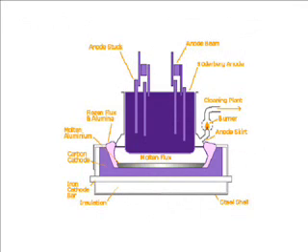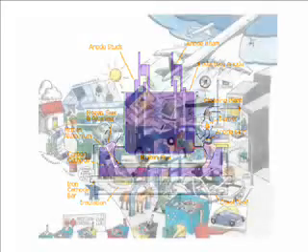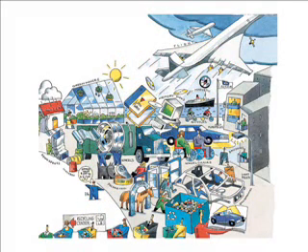The electric current flows between the carbon anode, which is positive, made of petroleum coke and pitch, and a cathode, which is negative, formed by the thick carbon or graphite lining of the pot. Molten aluminum is deposited at the bottom of the pot and is siphoned off periodically, taken to a holding furnace, where it is blended to an alloy specification, cleaned, and then cast.